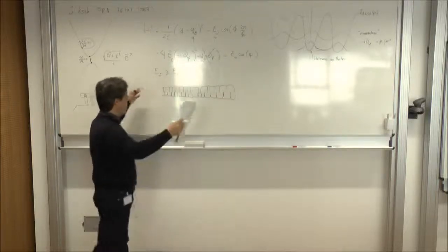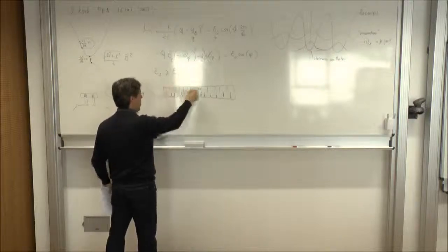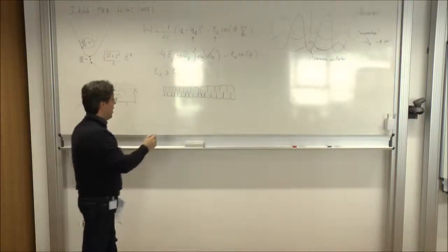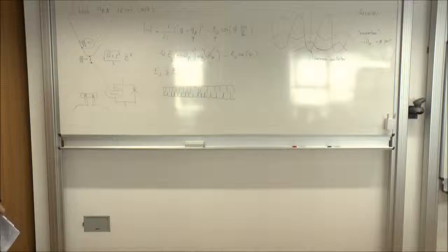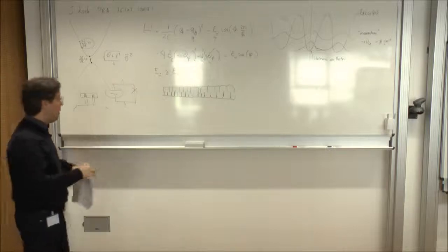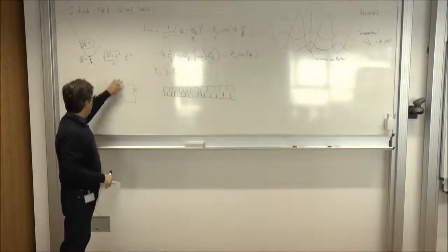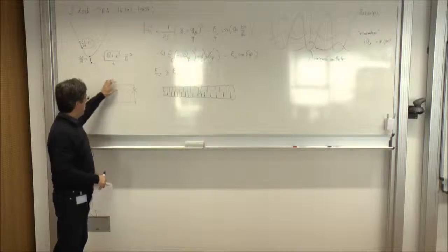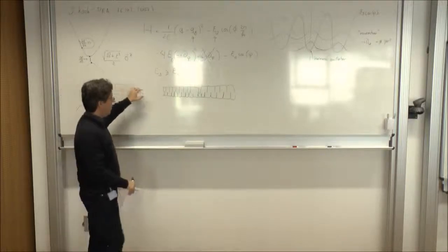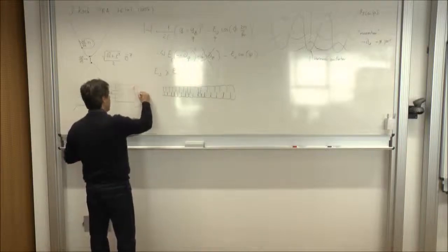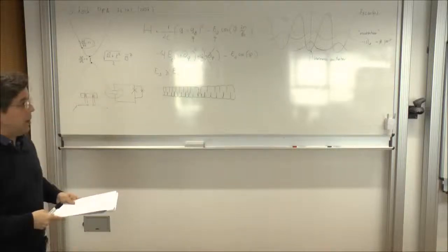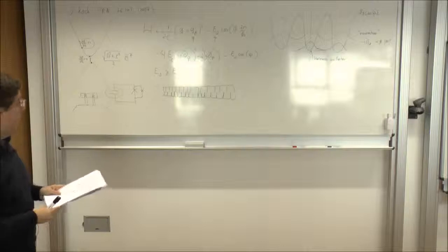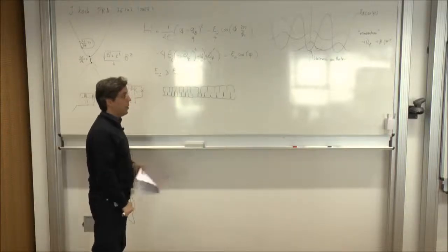We make the capacitors bigger, so there is more surface for charge to be accumulated, and it's proportionally much bigger than the region where we have the tunneling between the different segments of this island. It's now an isolated structure. It's not touching anything. It's just one body describing the tunneling between two segments of capacitor with a junction that is now a SQUID as before, which can be tuned. The dimensions are much bigger than the charge qubit islands that we had before, and this is what we account for in the capacitance.